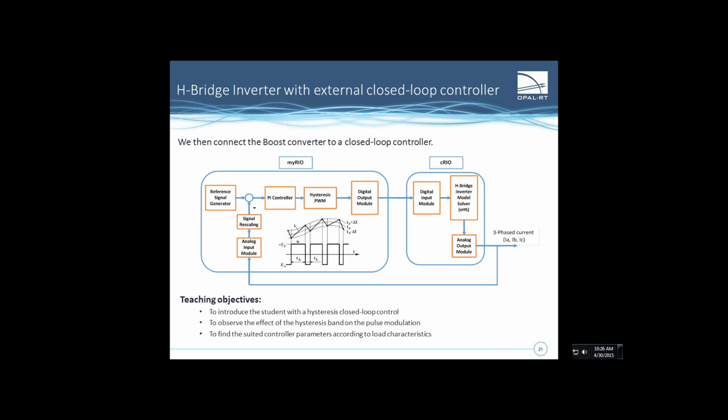So the students will be using a hysteresis control algorithm for that, and then they'll step through the different parameters within that hysteresis control to understand better the impact of the hysteresis band and the pulse modulation on the closed loop behavior of an inverter circuit.